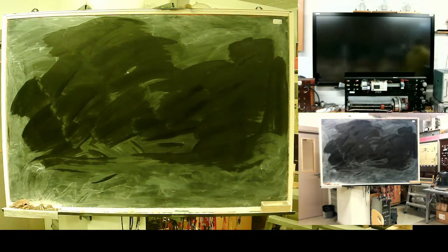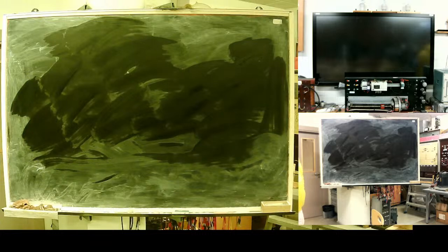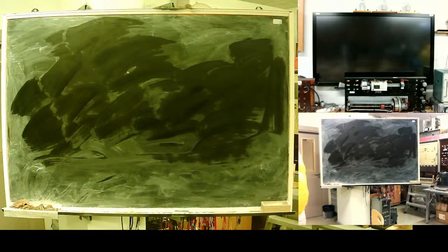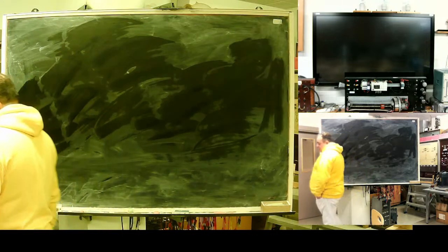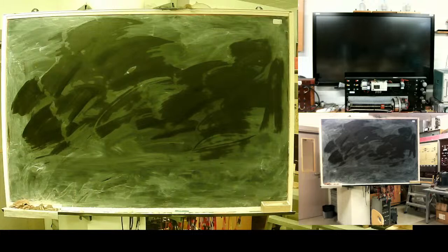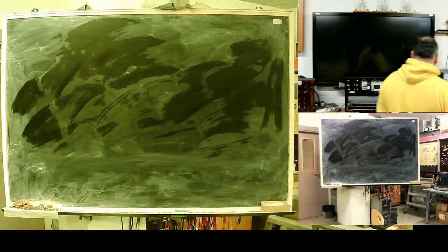Its child was so-called high frequency protection, which is based on a technique called power line carrier. We can use our power line as a data bearer, as a transfer medium.